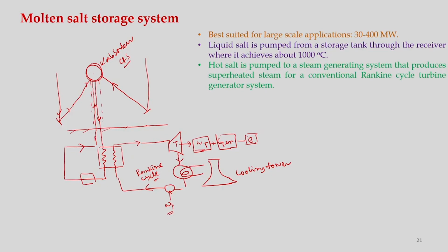Water flows, and the heat developed here will be carried by this water, and this is something like our boiler. So, steam will be generated, which will be expanded in the turbine, and electricity will be generated by using this generator, and then this has to be ejected. Okay. So, low temperature water will come here, and then the condenser will be there to cool the fluid, and it has to be pumped back by using this pump.